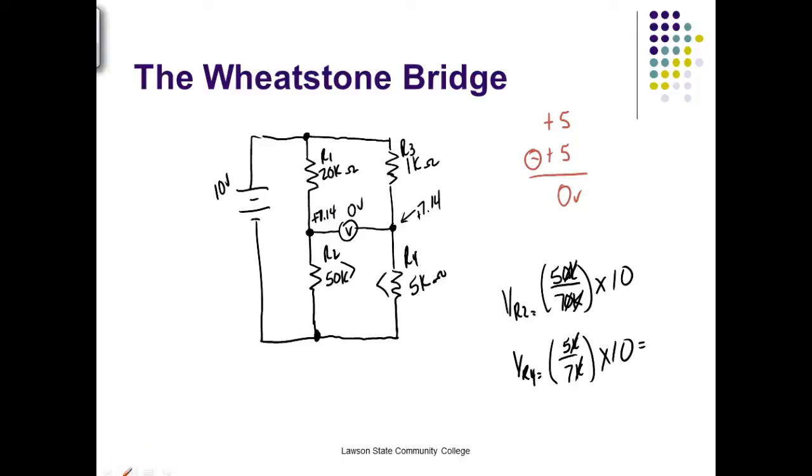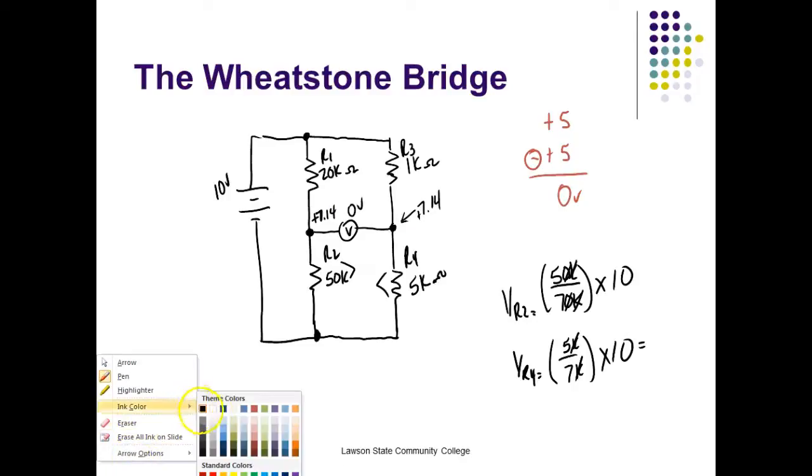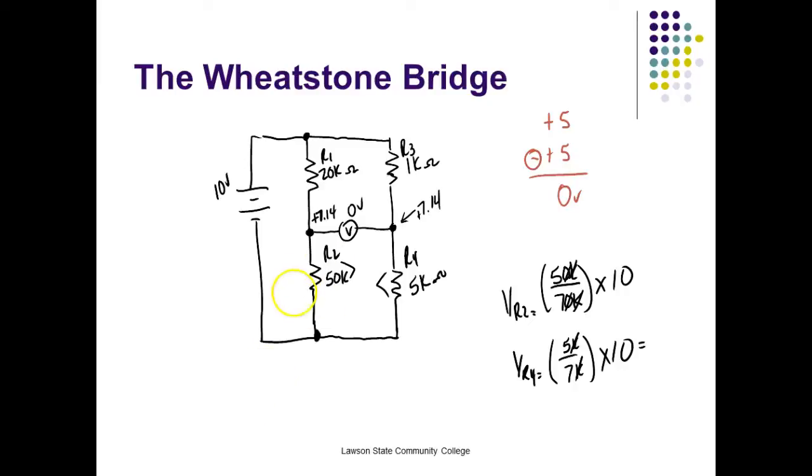So what we're saying is that if the ratio of these two matches the ratio of these in the correct order, in other words, I'm using little big, it could be big, little, so it has to be the same order over here on which resistor, where you put the big resistor and where you put the smaller resistor. But as long as the two ratios match, then we will have what we call a balanced bridge.